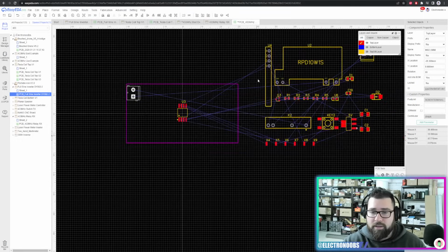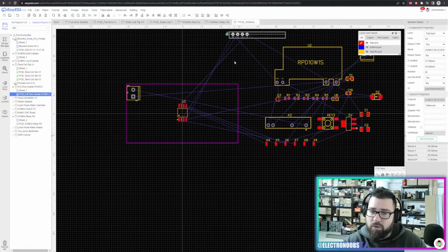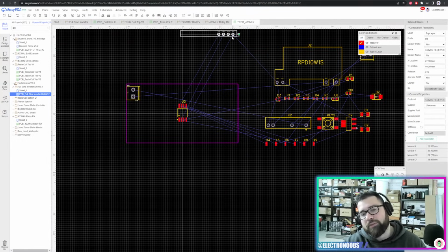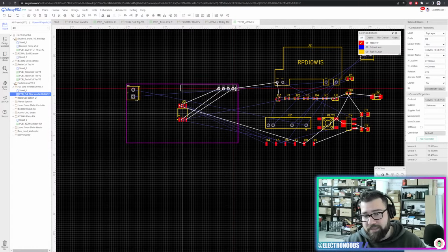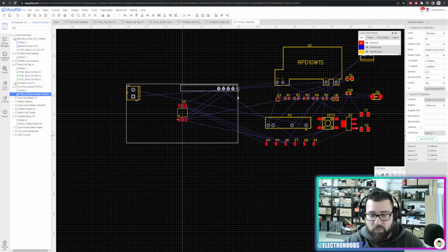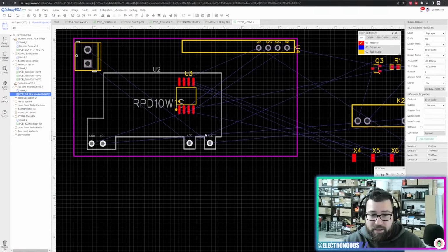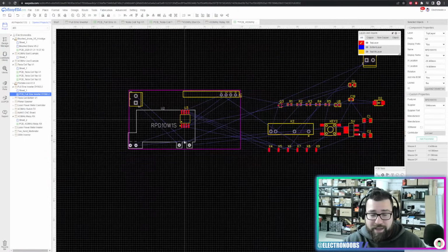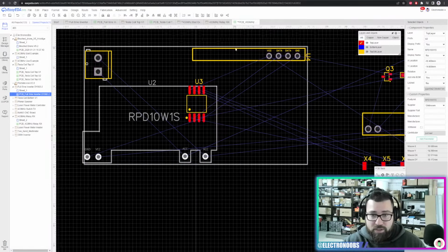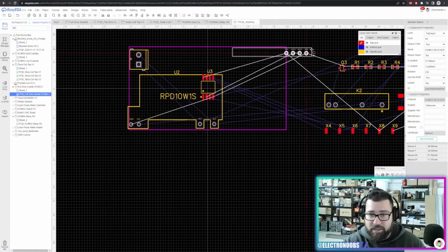The connector here. The radio also, as I told you before, you will try to place it on the outside of the PCB as well, because you don't want to interfere with the rest of the power connection, especially when you work with high voltage. So remember, this module here has AC input of 220 volts, and that will create a lot of noise, so you want to keep your radio connection as far as possible.